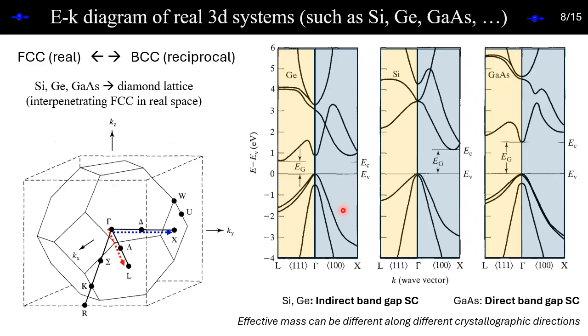Now how do you provide that? For that, you need phonons, because phonons carry much more momentum than photons. Only then is it possible, and that means the lattice vibration. That's why you won't get light in the reverse process here. Silicon and germanium are not good for optoelectronics, but excellent for electronics.